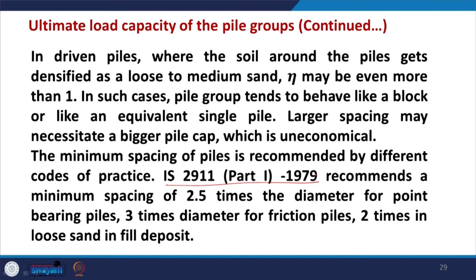Minimum spacing is for end bearing piles, this spacing S should be more than 2.5 D for the first case. But if you have friction piles, then spacing should be more, that means S should be more than 3 times D. But in loose sand deposit, the minimum spacing S can be 2 D.